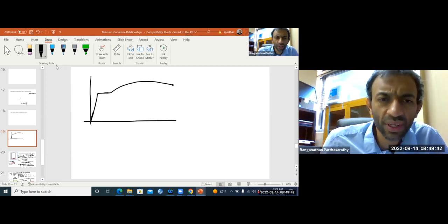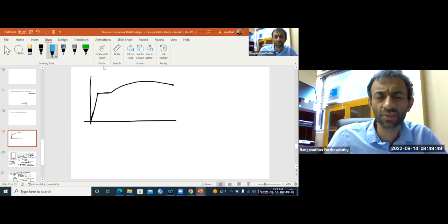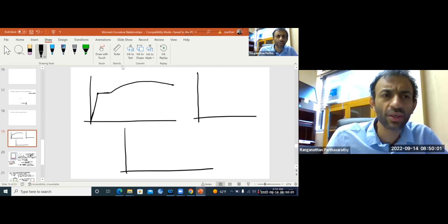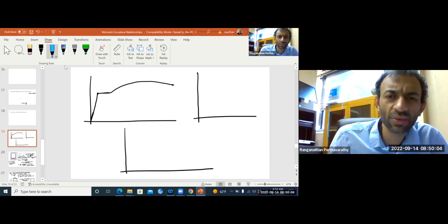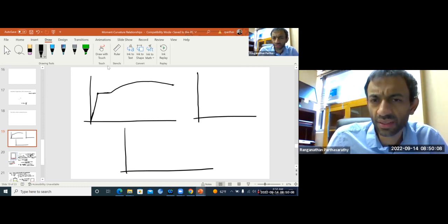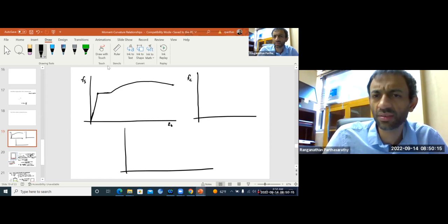So where are we at point 5? Point 5 is the yield point. So this is point 5 on the curve. Let me draw in parallel the curve, okay? Let's draw the concrete curve here, just so that you can get the full picture. What is point 1? For point 1, we are at the cracking moment. So the concrete stress-strain curve is, again, not proportional. This is Fs, epsilon s, this is Fc.